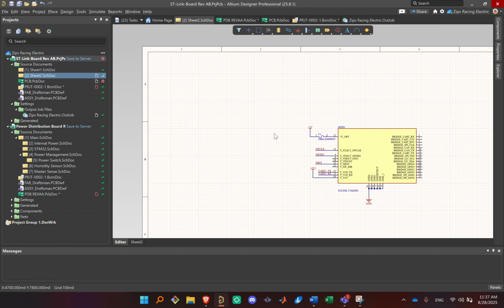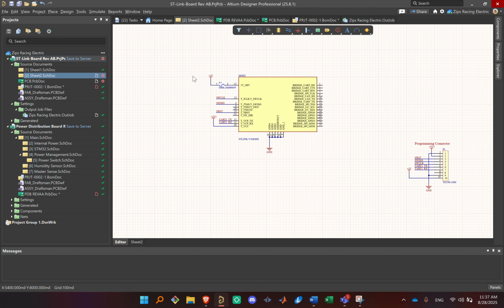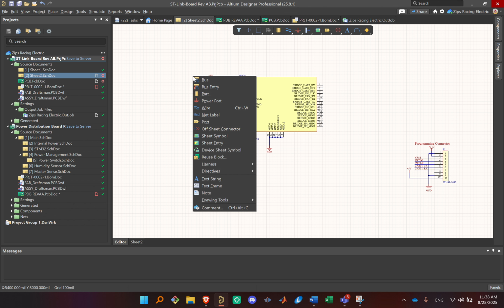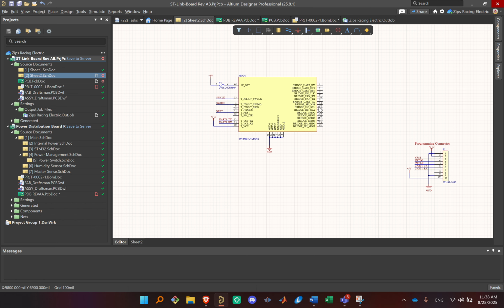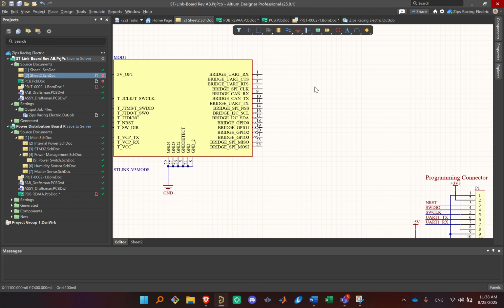Delete that. Yeah, so any kind of thing in Altium has a shortcut for it. We can go back to that place menu again. Some other ones that we do are placing a wire, right? So if you want to connect two things together, you do that by hitting Control W, and then you can see this little cursor gets brought up, and that'll let you route a wire.